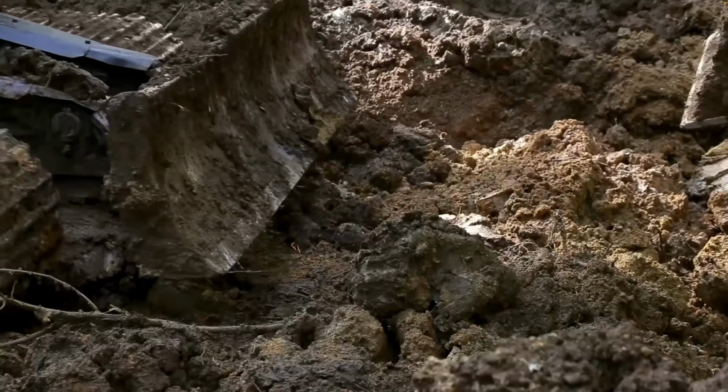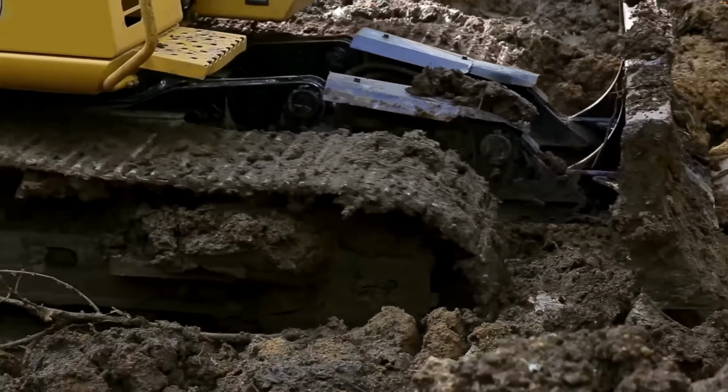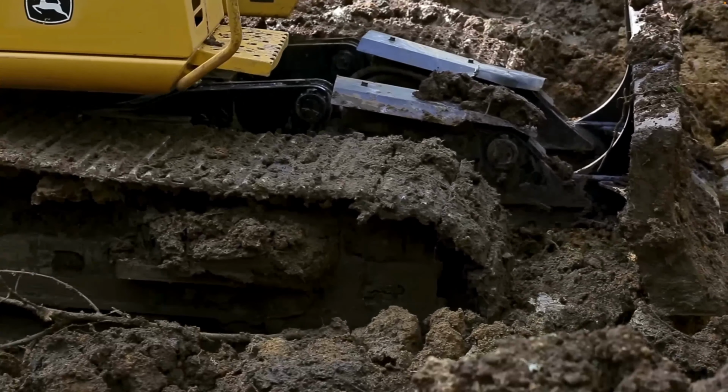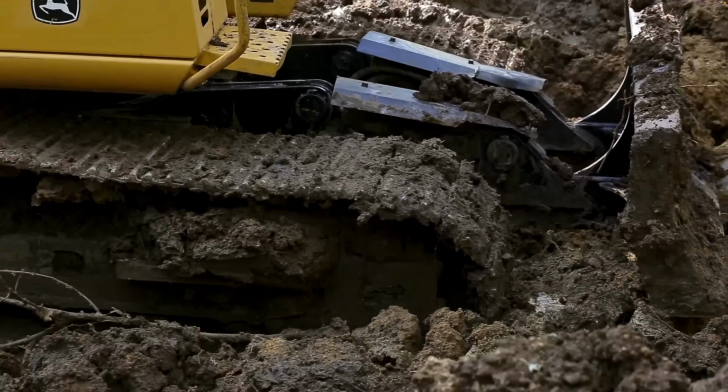We can also track roll with the machines we're working with, bulldozer, excavator. On small ponds, I have actually used a rototiller to till and create a compacted layer, and doing that as we go all the way across. The rototiller actually creates a good compacted layer below it in the clay soil. So compaction is really important.